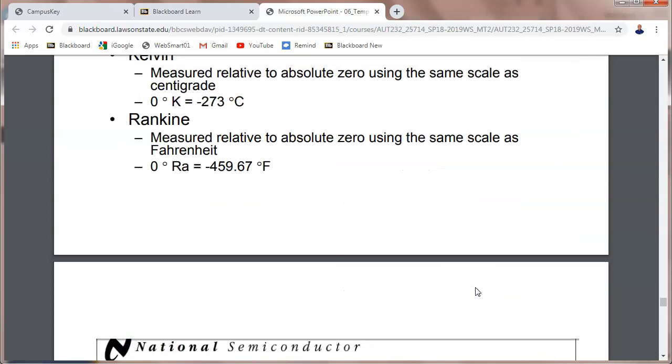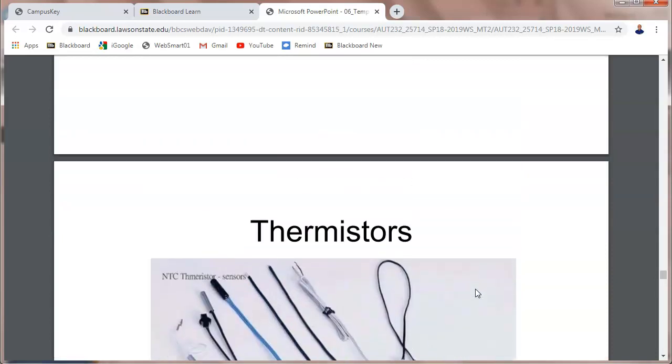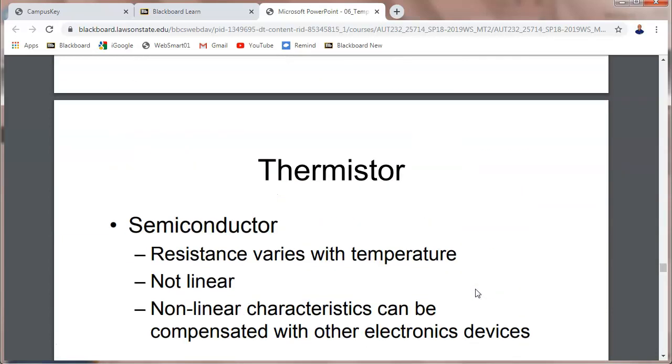It depends on the math formulas and what they do. A lot of times they'll use either Rankine or Kelvin. We show you how to calculate the actual dynamic resistance of a p-n junction, and they use Kelvin in that. It turns out to be approximately 25 millivolts over emitter current. Yeah, we use 25 millivolts over. It's interesting to see all the math of how these physicists come up with these numbers that we use as constants right now.